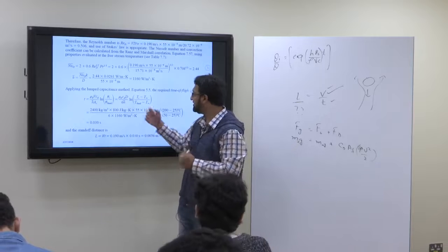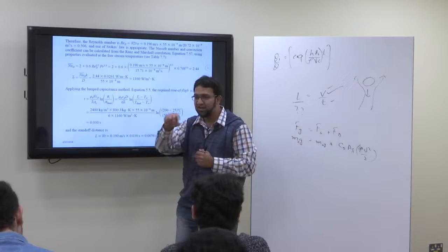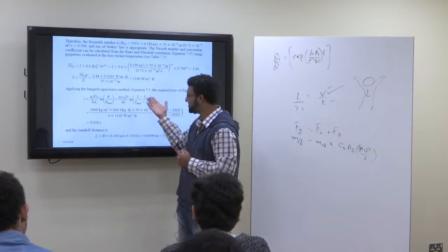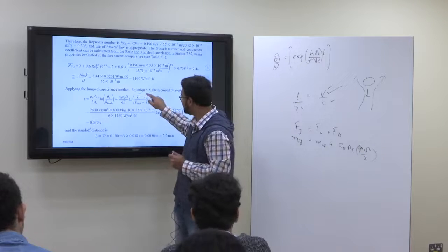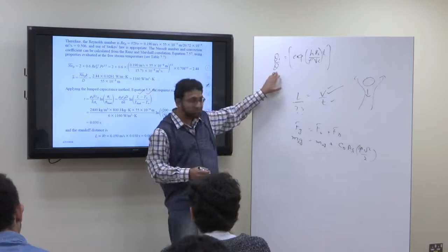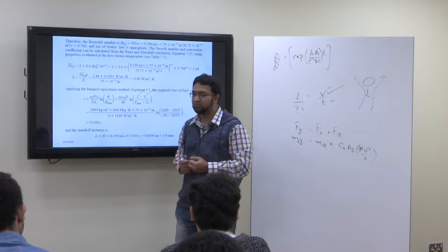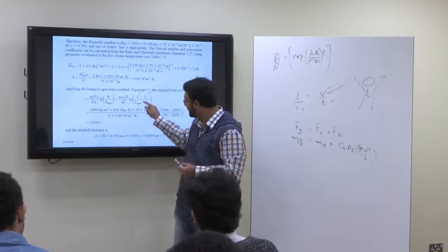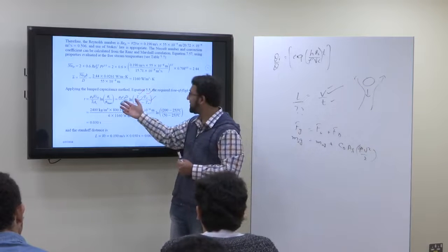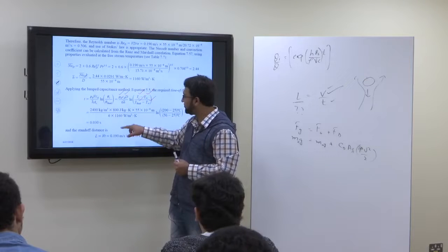So now if you see in this equation, theta I is what? Theta I is Ti minus T infinity. Ti is T initial, so you know what is Ti. You know what is T infinity. So this thing is known, this thing is also known. Theta means whatever temperature you want to find, so this is theta final. Theta final will be T final minus T infinity. T final you know, and T infinity you also know. What about the other parameters? The parameters are the rho of the droplet and the specific heat of the droplet.